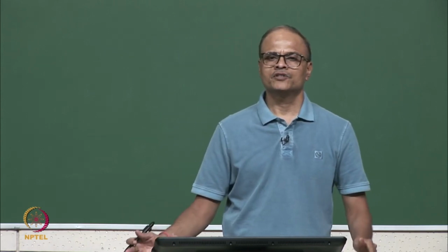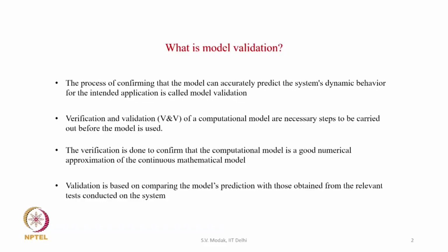The next step is model validation, which involves comparing the predictions made by the FE model with some reference data identified from the test. So therefore the validation is based on comparing the model's prediction with those obtained from the relevant tests conducted on the system. So for the purpose of validation, we require some reference data against which the FE model predictions can be compared. So by comparison, then we can arrive at a conclusion whether the FE model is accurate enough in making the desired predictions. So let us now look at what is the need for FE model validation. Are there any sources of possible inaccuracies in the FE model? Let us try to discuss that.